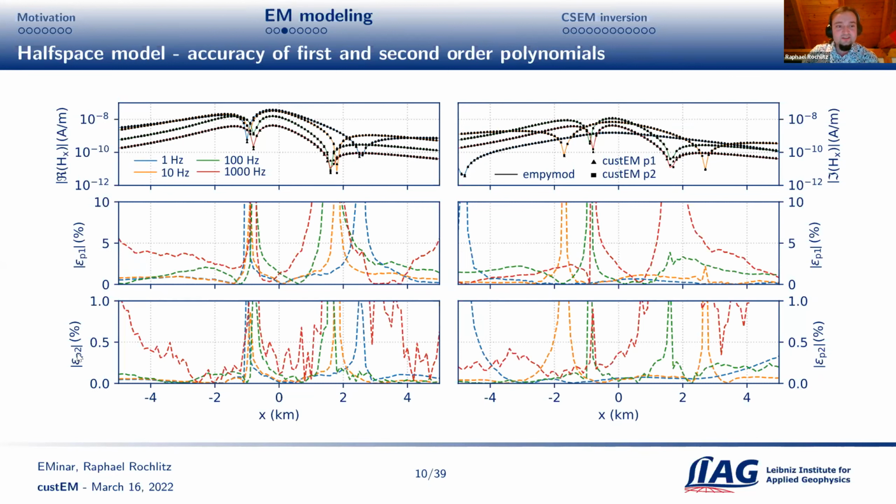The P2 computation on the coarse mesh goes with an error scale from 0 to 1%. So if you compare the curves, we have about 1 order of magnitude more accurate results with second order edge elements in finite element analysis. This is what we are doing in all remaining examples I will present. It's very beneficial to get accurate results with comparably fewer computational resources than for P1.